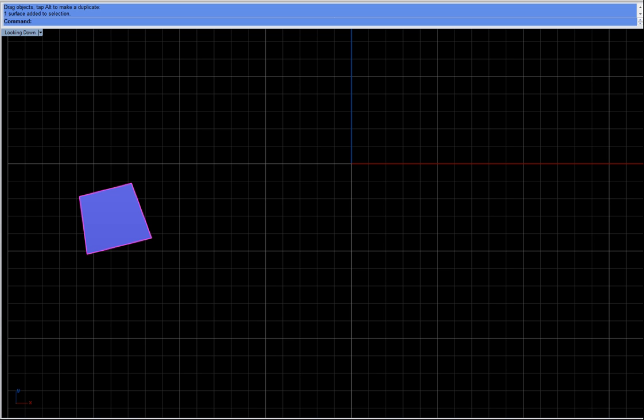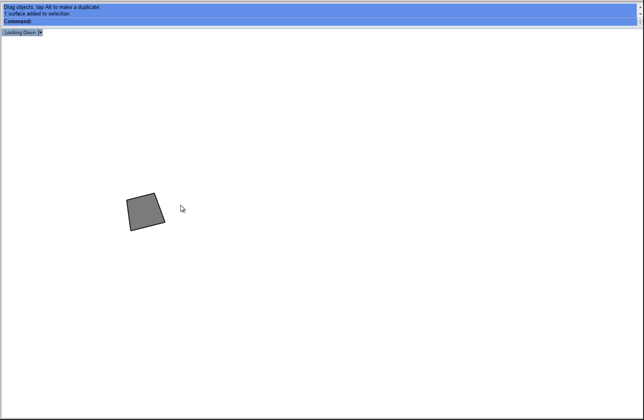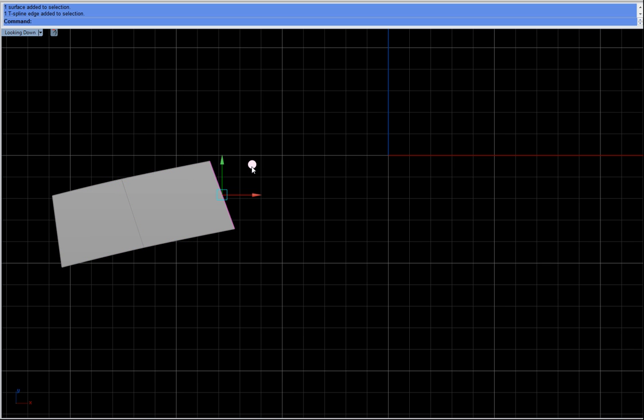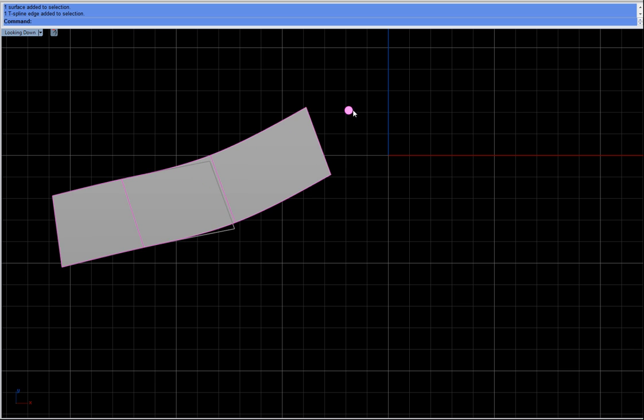So with this one face, we can go after our design from here. Hopefully this is a little easier to see in the video. I'll switch over to edge mode here, and I'm just going to grab this edge, and hold Alt. Actually, let me go back to just regular shaded. I'm going to hold Alt, and I will use my handle here, and drag another face out. So I'm just extruding by holding Alt. And I can just continue to do this.